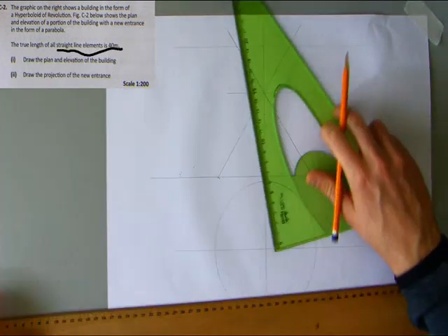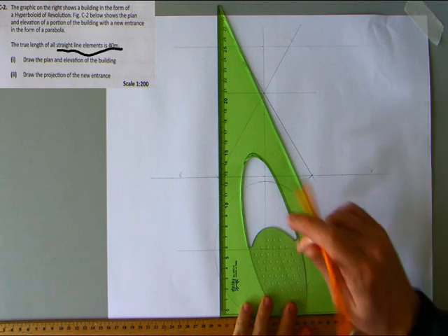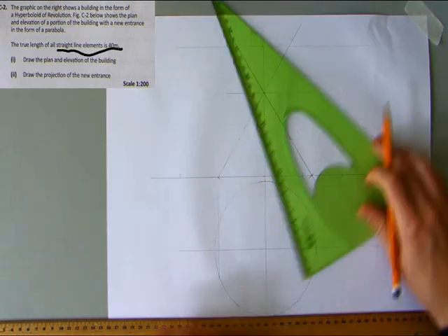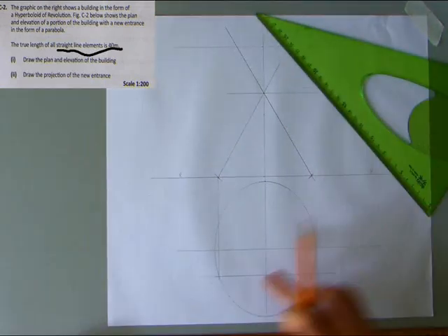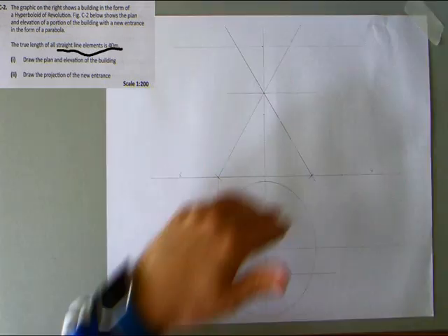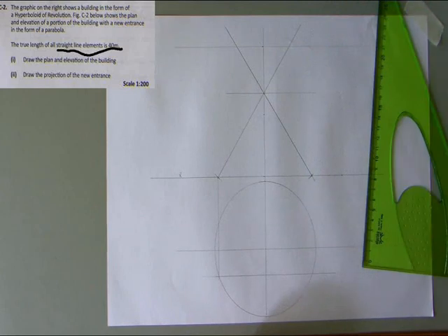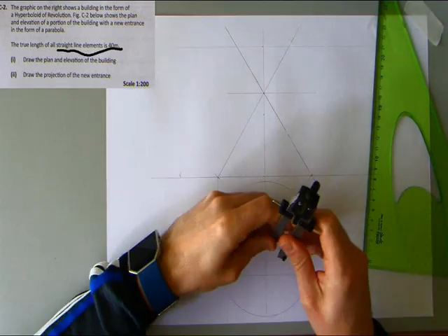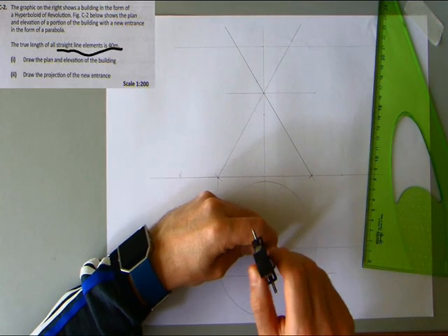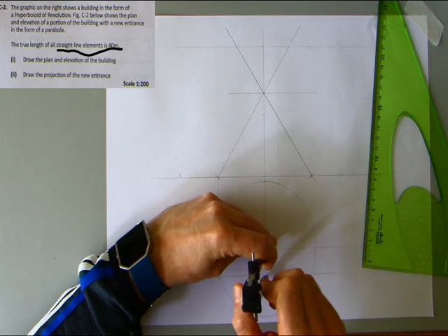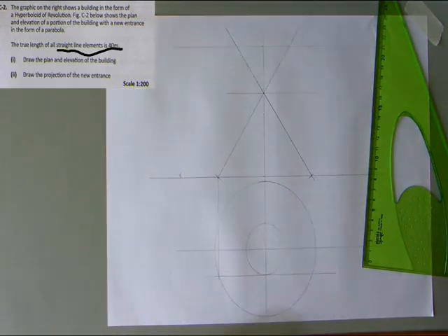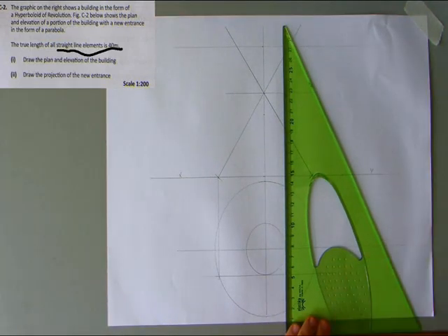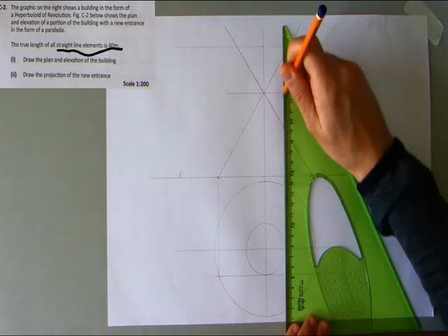What I'm going to do is bring that point down to my base circle here, and that's our vertical cut. The horizontal line is the vertical cut coming down, giving us our measurement for the throat circle. So there's the measurement for my throat circle. I can now bring that up to my front elevation view. There's the measurement there.